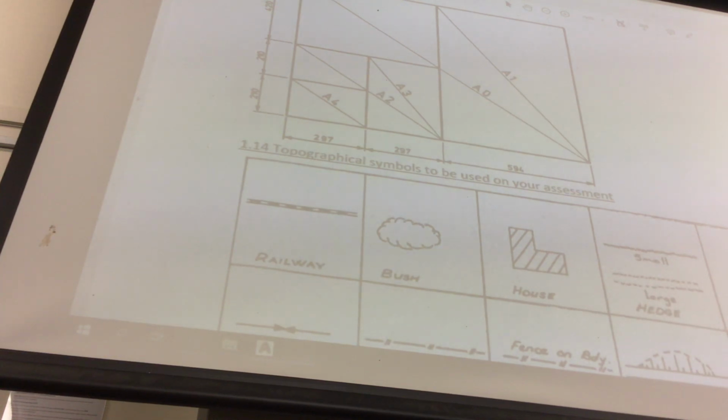I have a question on this too, and I guess the most important thing for students to know is that in area size, it doubles every second size of paper. So an A4 to an A2, sorry, it's 4 times the area size, I beg your pardon. So from an A4 to an A2 is 4 times the area size, but the scale is 2 times the difference. From an A3 to an A1 is 4 times the size, the scale is only 2 times the difference.